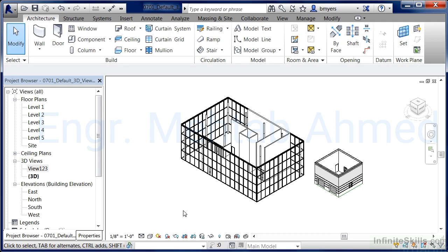One other property of it is if you're working in what's called worksets, which means multiple people can be working on the project at the same time. If that's been enabled, then whenever you select on the 3D View button, it will have 3D and then your name after it. What this is indicating is that that's your default 3D view as opposed to other people who are working on the project's default 3D view.